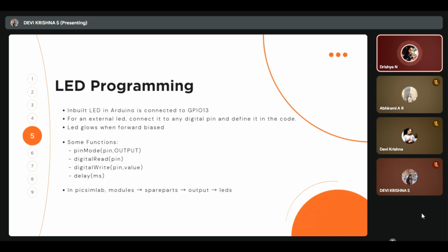The conversion process can be broken down into major steps. First step is sampling, where the continuous analog voltage is sampled at periodic intervals in time. This yields discrete time snapshots of the analog signals. Next step is quantization. The amplitude of each sampled value is mapped to the nearest one of a discrete set of levels. The number of levels depends on the resolution of the ADC.